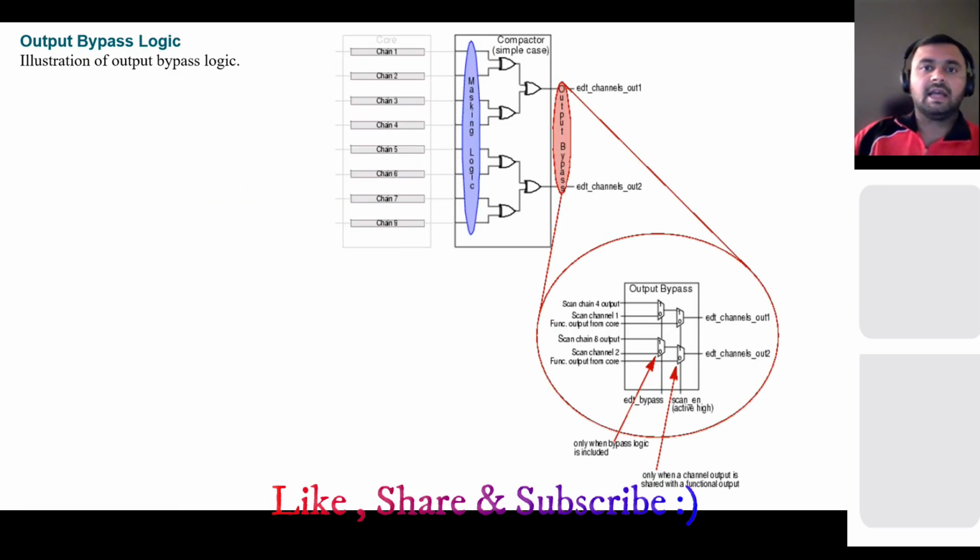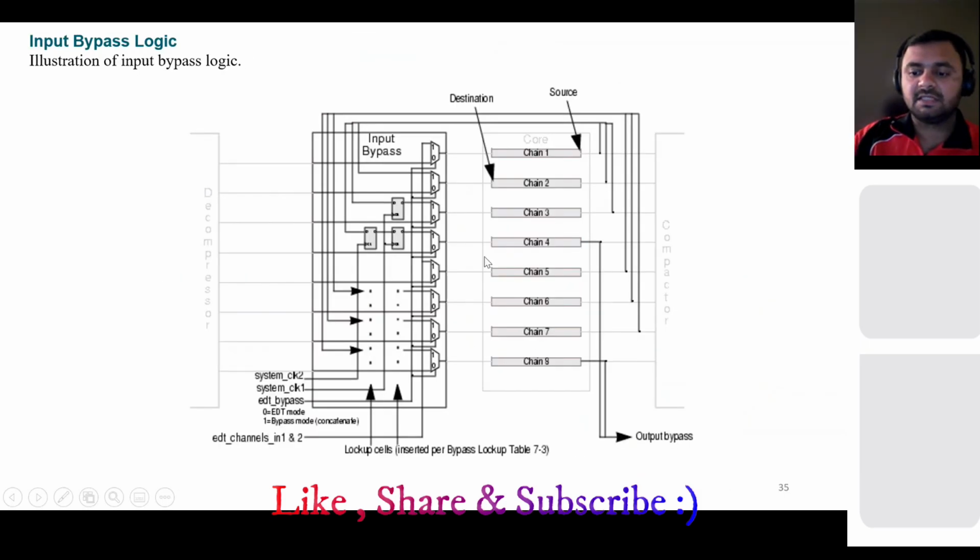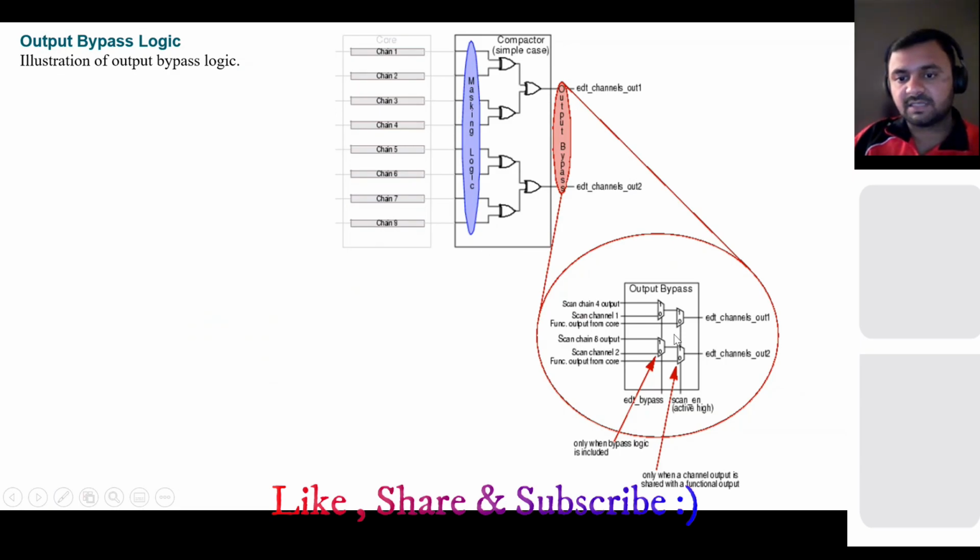And this is your output bypass logic, how it bypasses, which we saw here. This bypass mechanism is shown more specifically here. Basically you concatenate all the internal chains and make a logic here for longer chains, and it will bypass. Bypass in the sense that it will concatenate 4 of the chains and make a single chain.